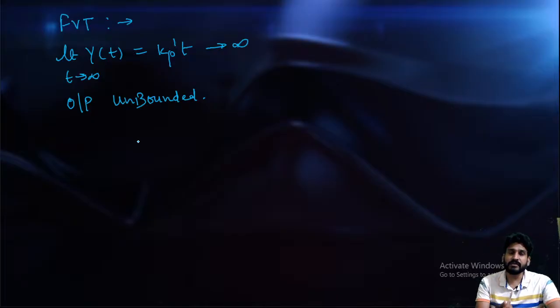It means that my system is going towards the unsteady state. The system has no capability to get back to its steady state on its own. खुद अपने आप खुद ये steady state पे नहीं आ सकता. So it is not possible for the pure capacitive system to get back to its steady state itself. Is it clear or not? So the response of the pure capacitive system for the unit step input is unbounded.